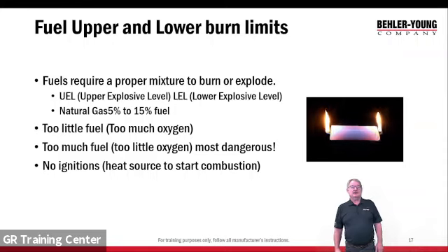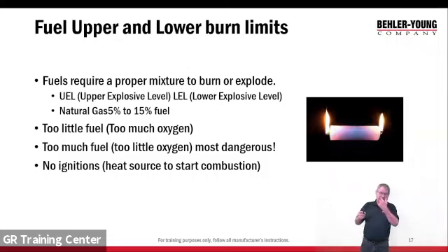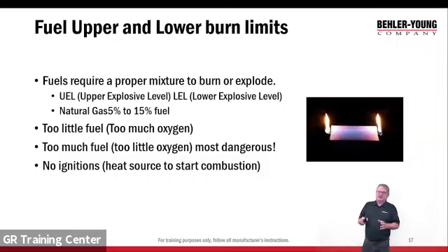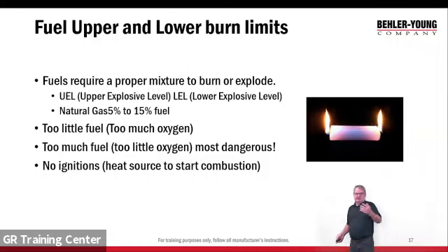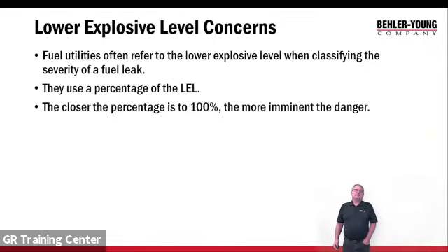Okay, no ignition. So I can have the perfect amount of air, the perfect amount of fuel, and if I don't have a heat source, the proper heat source to ignite it, I can't ignite it. And I say proper heat source because different fuels have a different ignition point as far as temperature. So we need the right amount of heat or ignition for that particular fuel. So, upper and lower burn limits of a fuel.